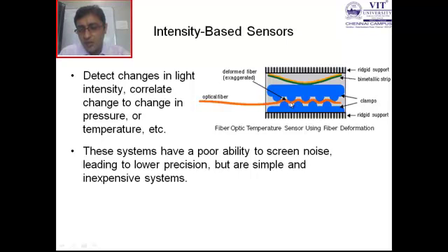Now when the deformation happens, you see a physical deformation at the teeth's interaction between the two deformers, wherein the diameter of the cladding is disturbed and it undergoes a physical deformation. This physical deformation allows the light which is traveling through the core to escape. Because total internal reflection is dependent upon N1 and N2, and when N1 is subjected to a refractive index change, the total internal reflection is also disturbed, because of which the light tends to escape. The light intensity which is escaping here is directly proportional to the pressure you apply on deformer 1.